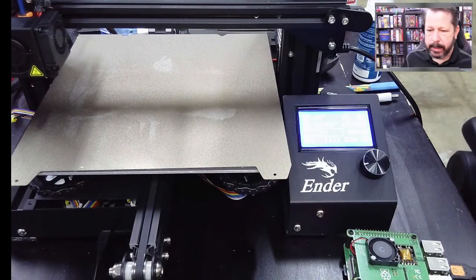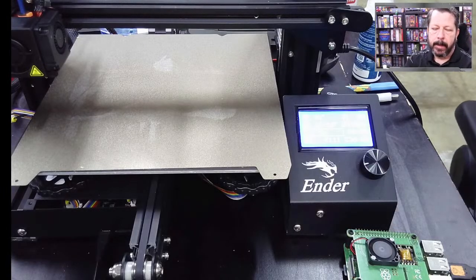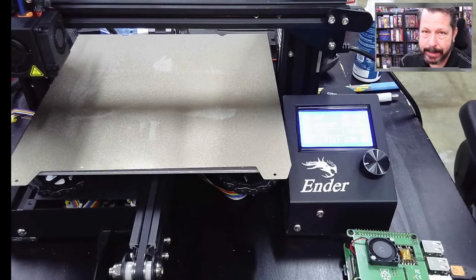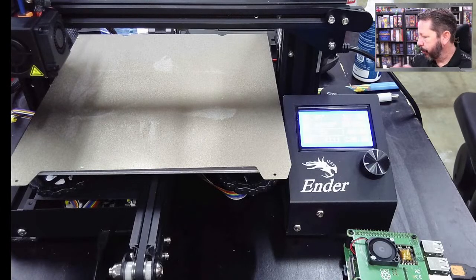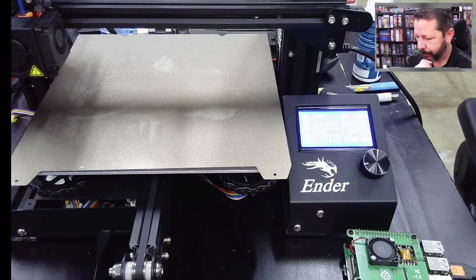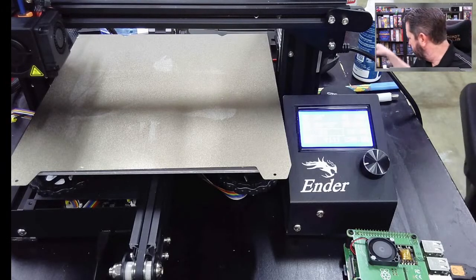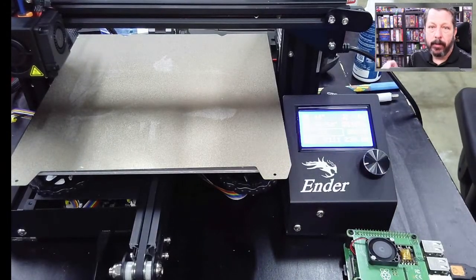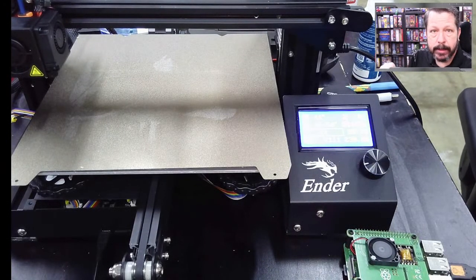All right, so the idea with this one will be we will go in, print our little cube. Again, probably a bigger one would be more realistic, more useful, but we're going to print the smaller one just for time. And then we will measure with our calipers the actual wall thickness. We'll measure it 2 times on each wall. So we'll have 8 measurements. We'll average those.